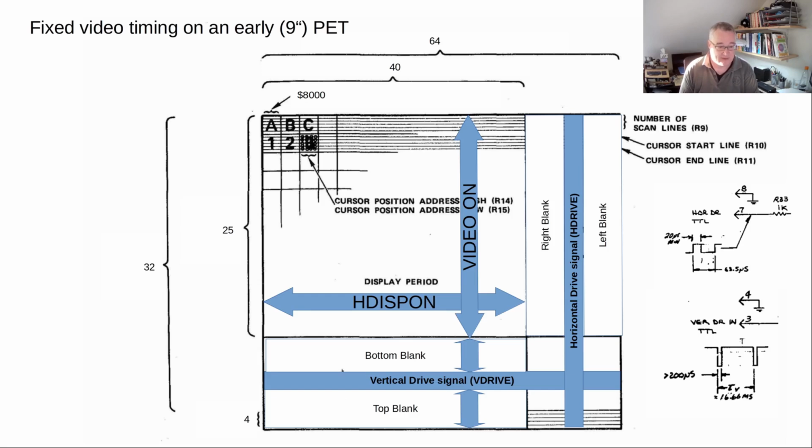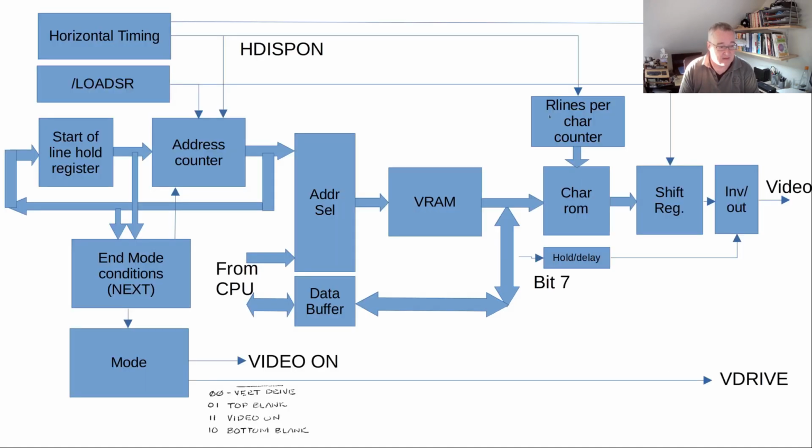And then we get 260 raster lines with 64, that's also going to be important, 64 microseconds for a raster line, and this is 16,640 cycles per screen, which is almost NTSC compliant. So that's very ingenious, reusing that address counter.